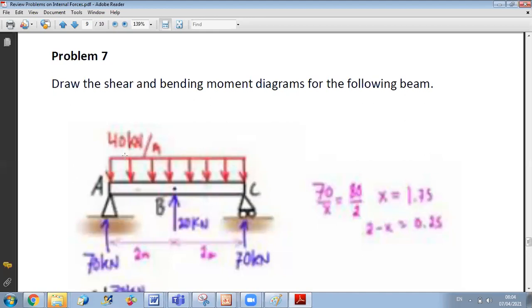So here, since you have a symmetry in your beam, because you have a distributed load that is symmetrical with respect to the center, and you also have symmetry in the supports because both develop Y reactions, and no X force, so no reaction along AX, then we can say that in this case, because of the symmetry, we can directly just find the shear variation between A and B and deduce it between B and C. And this is what we did last time.